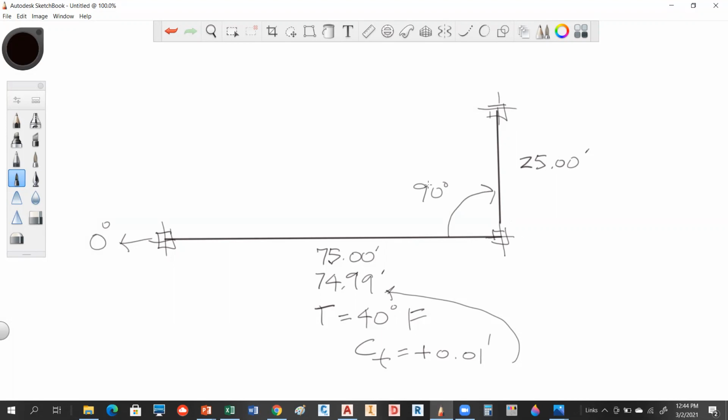Now you're not going to check, or you're not going to just assume that that angle's correct. Who can tell me what we're going to do to make sure that that angle's good? We'd flip the scope. Right, flop the scope, and then turn that back. When you flop the scope would be basically facing this way, right? And when you then turn it back to this, it should be reading 180 plus or minus. So you'll set zeros again, and you'll return the 90 and just make sure that you're hitting what you said you did, okay? That's just a double center on this. So we're going to double center that. All right, is everybody okay with that?